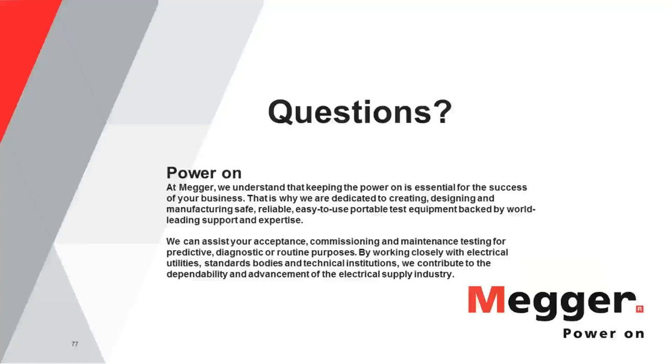Resistance should not change with the voltage that you're applying. It should be a constant result. And if you have a resistance that is decreasing as you increase the voltage, then it's an indication that there might be some partial discharge inside the insulation, and that you might need to take some maintenance actions on that insulation.